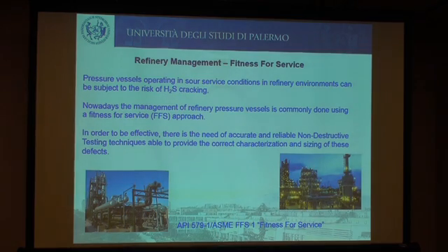As we know, pressure vessels in a biomass environment can have hydrogen sulfide cracking, even though now there are materials that can resist this problem. We have many assets to be inspected to see if there are cracks inside, and the size of this crack is important, and the location and the thickness are also important to be detected.